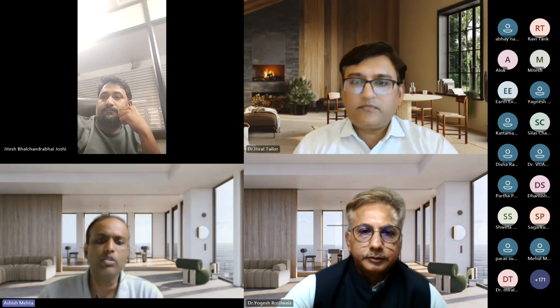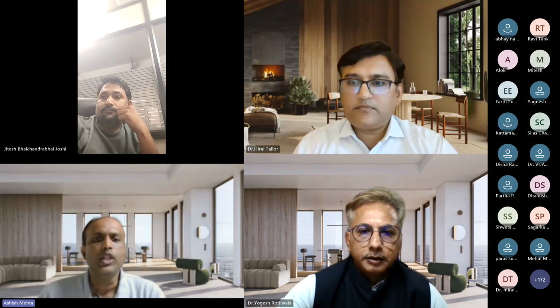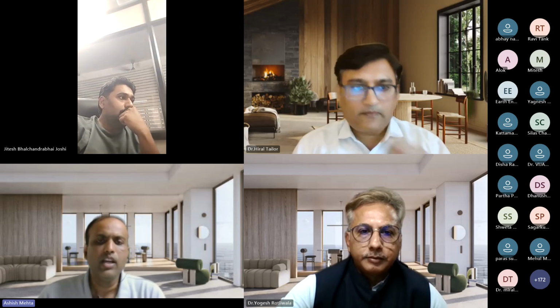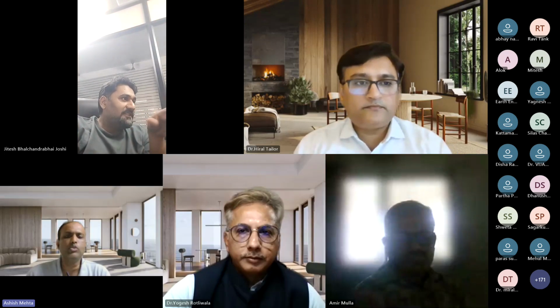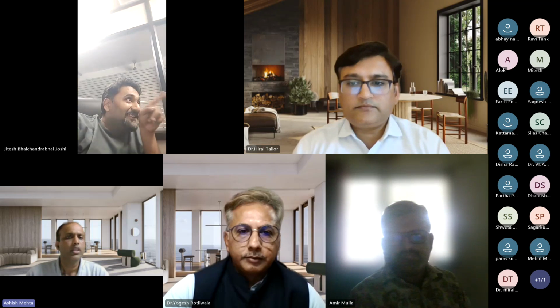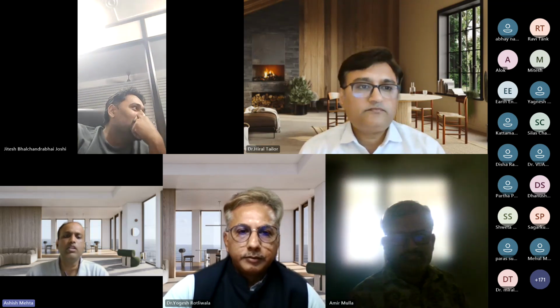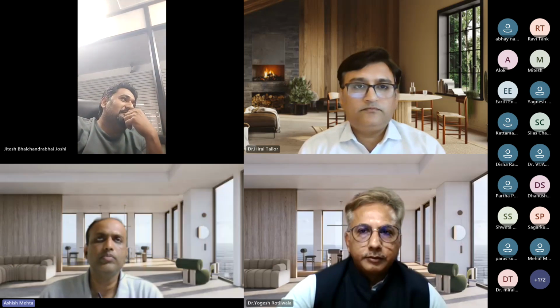electrochemical oxidation and coagulation process. The very good result we could achieve was the color reduction. The textile industry faces a lot of issues with color, dyes and pigments. We could achieve in the range of 95 to 99% color reduction using this technology.